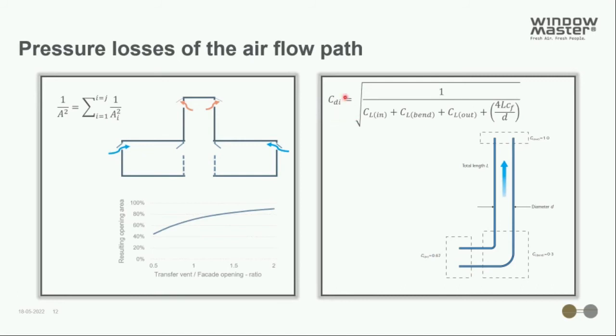We just need to replace the discharge coefficient that we find for our duct system with the discharge coefficient in our calculation, which before for the CIBSE calculation was 0.61.